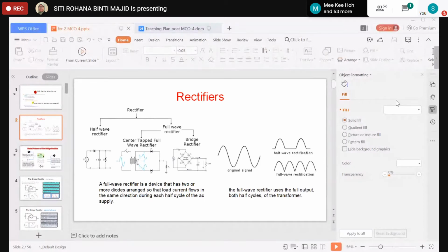Another advantage of the bridge rectifier is that it needs fewer turns of wire in the transformer during the winding process. The transformer used in the rectifier is small and lighter compared to a two diode full wave rectifier, and because of the fewer turns, the cost would be less.